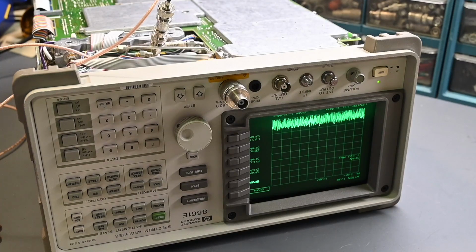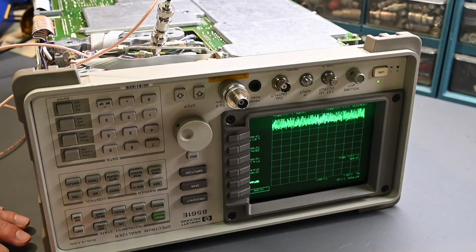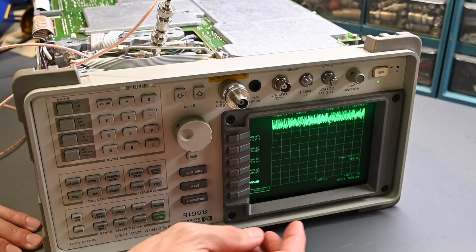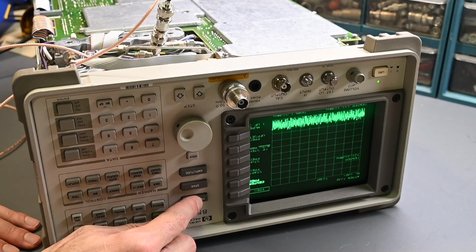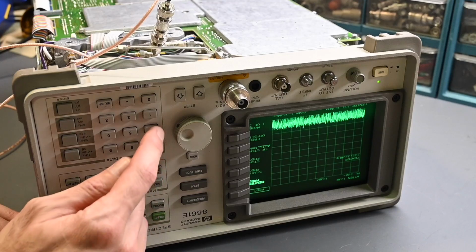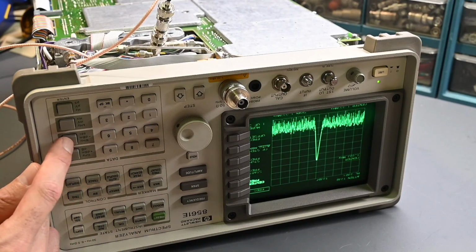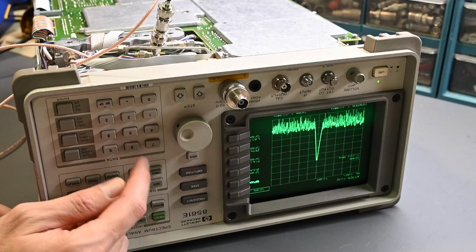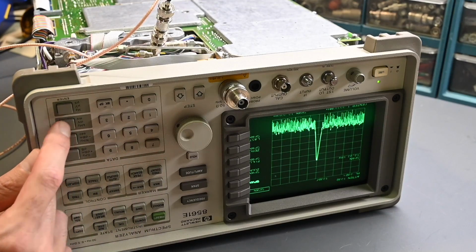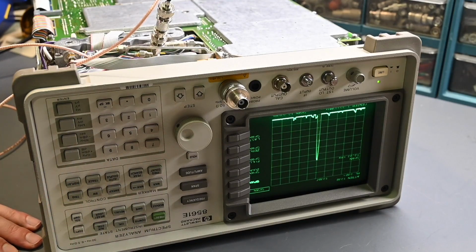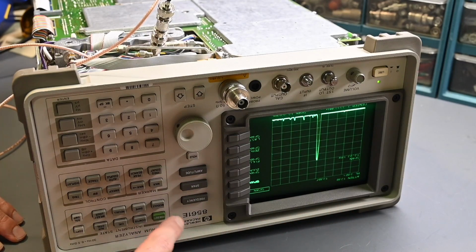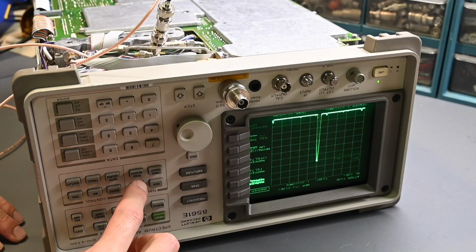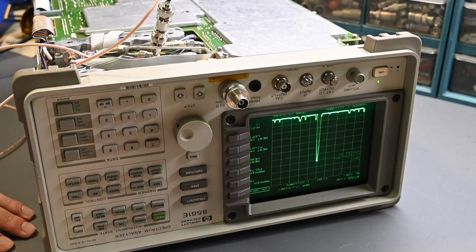And now, of course, this is upside down because we're working at the bottom of the instrument. So I've got to do everything sort of upside down and looking past the camera here. So let's go to frequency, make the center frequency 1 megahertz. Let's make the span, let's say, 10 kilohertz, nice narrow span right there. And so let's get the marker on here, do a peak search. So it's reporting that that's minus 30.5 dBm. All right.